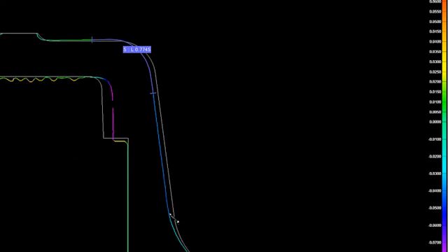Measuring a radius or diameter is performed by selecting the points along a radius to define your circle. At least 3 points must be selected to best fit a circle. Right-click to accept the circle, and right-click again to exit the mode. The last of the basic measurements is the length mode. This measures the chordal length between 2 points you pick. Right-click to exit this selection mode as well.